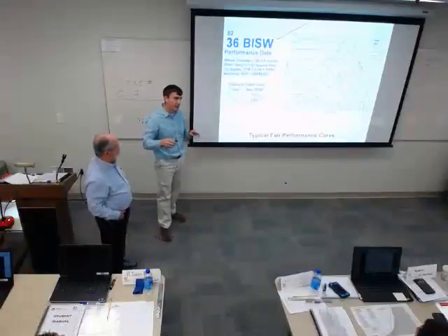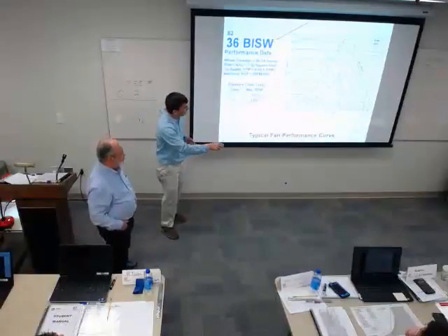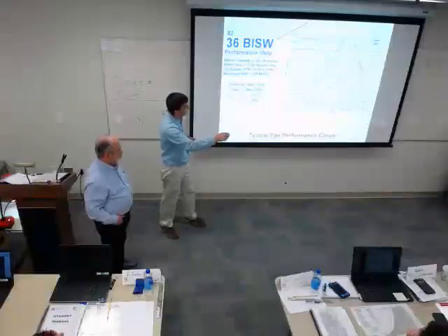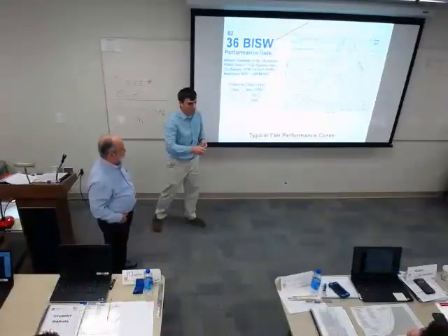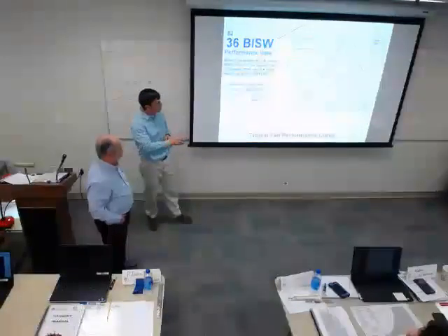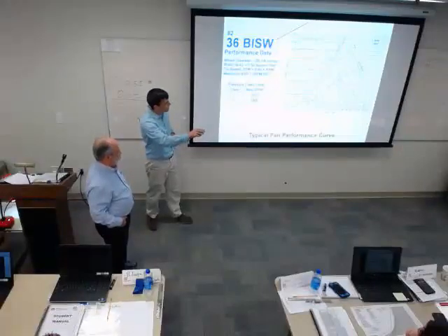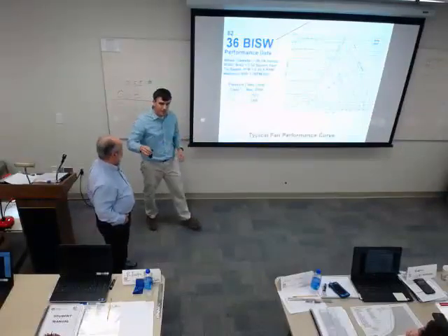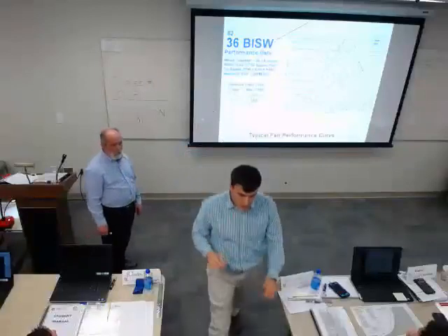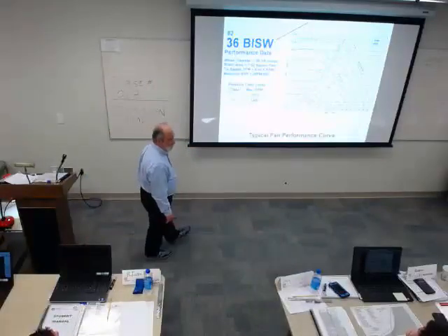Does that make sense? You've got the physical construction of the fan, which is part of where this number comes from, and also you never want to be on this flat portion of the curve, because you've got multiple airflow rates this fan can potentially operate at the same static pressure. That's part of how you get that bloop, bloop, bloop sound. Hope that made a little bit of sense.